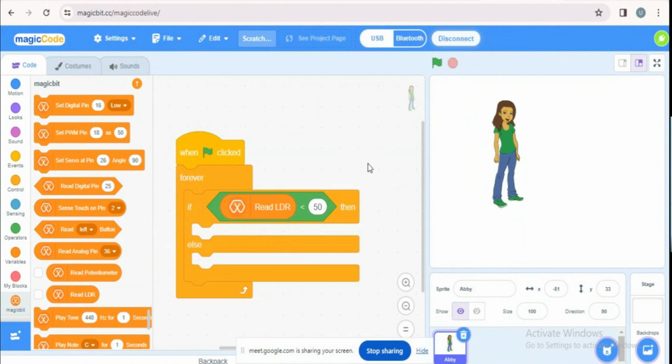So as we need to detect whether it is night time or not, we are going to check whether the reading from LDR is less than 1500. If this is the main condition, what should be the opposite of that? Reading of the LDR greater than 1500. If it is greater than 1500, we are assuming it is daytime, that means more light in the environment, so we can turn off the lights. And if the LDR reading is less than 1500, then we'll assume it is night time or the environment is dark. So we need to turn on the light switches, right?